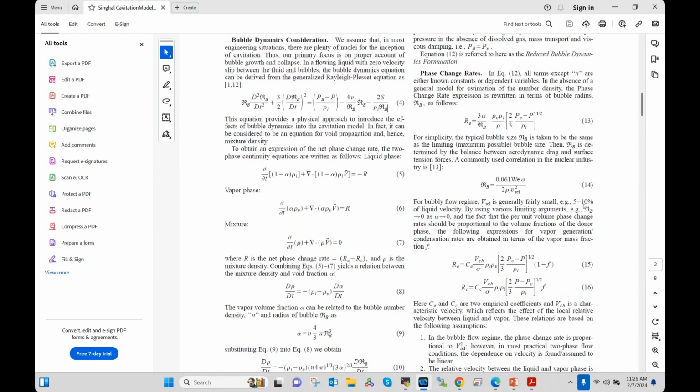The next question is from Gabor. Which cavitation model is the most accurate for centrifugal pumps? I think we found that the constant gas mass fraction model will do a good job for most applications. But in some cases, for example bearings, where you need the inlet and outlet air to be specified, you have to use the variable gas mass fraction model.